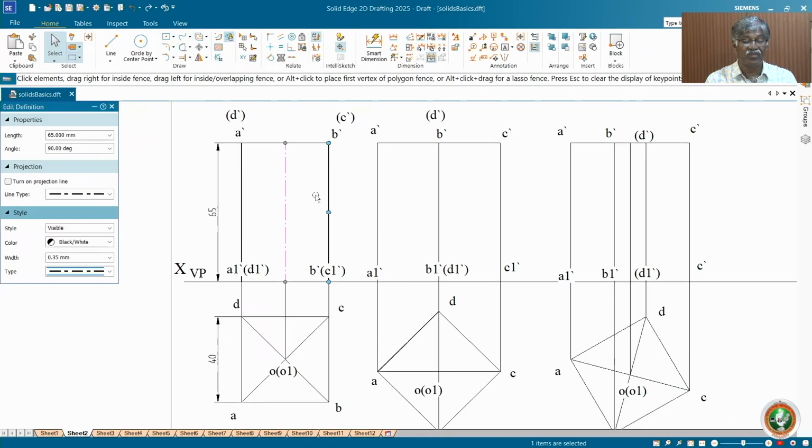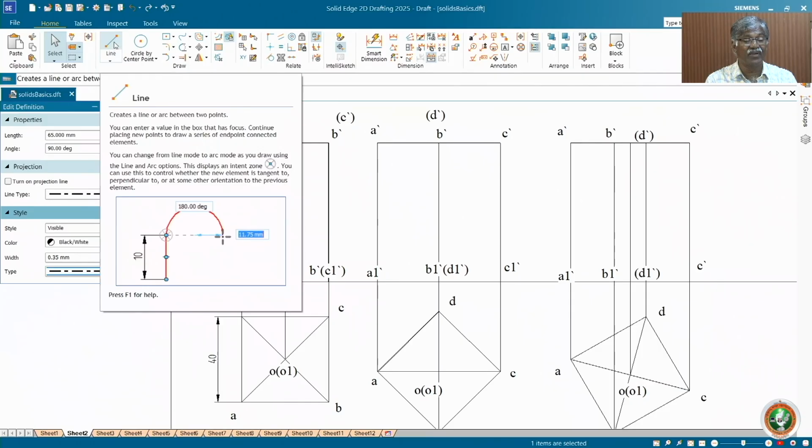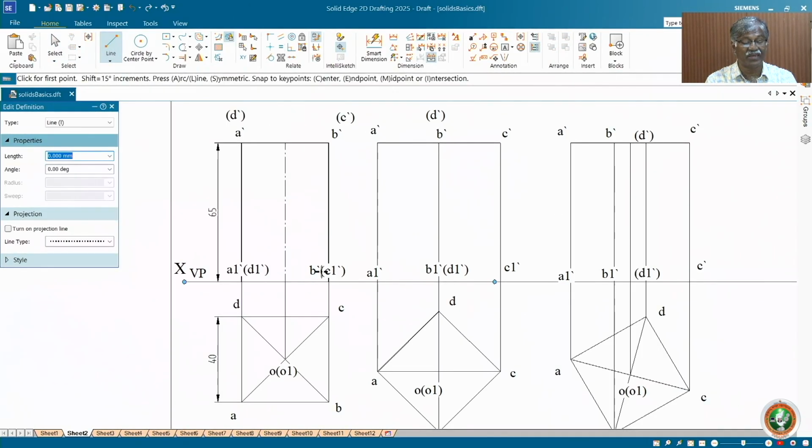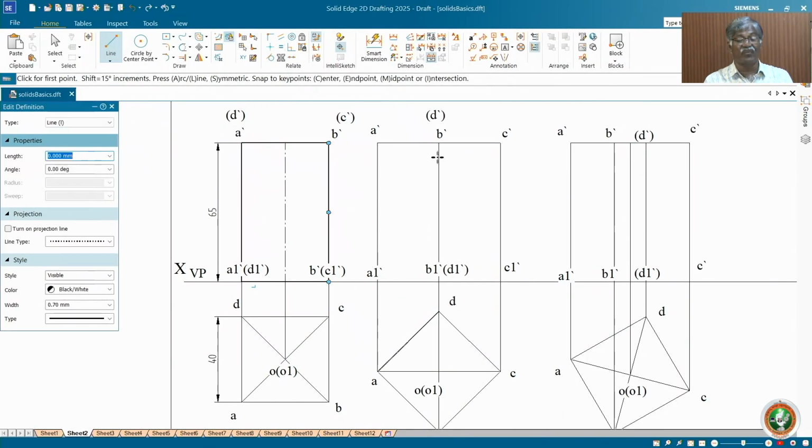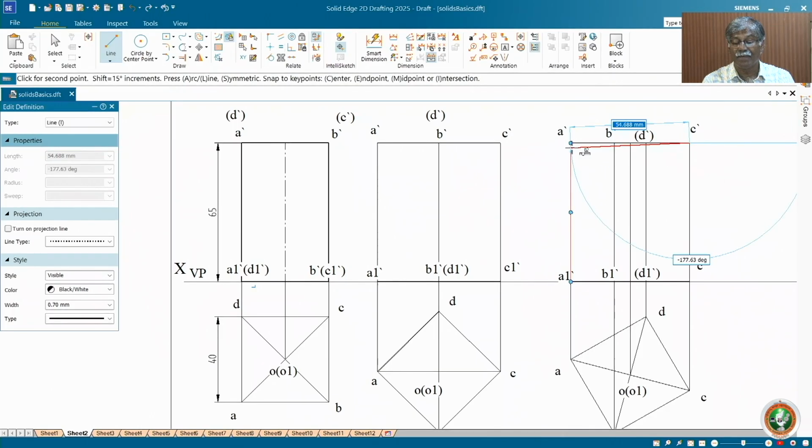All the time you should draw the top and base as dark lines. Normally we take the XY line as reference and don't complete it, so you should draw a dark line for this. It is the usual thing we forget. You should darken this also. Redraw once again, otherwise modify it, that's all. I always prefer this for all problems. I keep it because the top face and base are always visible.